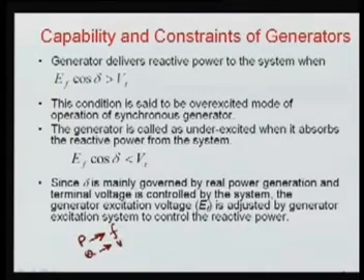So the delta change changes real power, and therefore the frequency, and your excitation voltage will change your reactive power, and therefore the voltage of the system. So these are basically the couplings. Normally we call them the P delta coupling and the QV coupling, or you can say PV decoupling and Q delta decoupling. These are used in load flow analysis and other things.